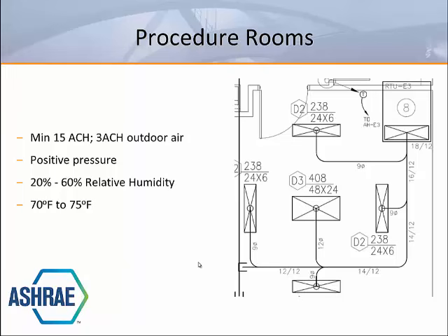returns. Design can be implemented where the system can be operated at 25 CFM per square foot to meet the lower air change requirements of a procedure room, and when operated at 35 CFM per square foot to meet the air change requirements of an operating room.